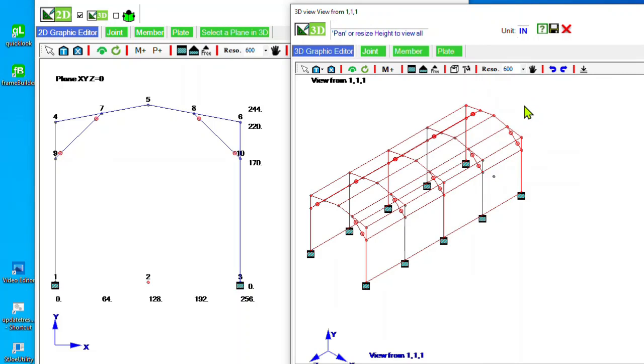Look at the 3D graphic, we have interframe members connecting among supports. We don't need that, let's use the box button to isolate them, thereafter, tag and remove them. There are 2 action buttons unique to the 3D graphic editor. The first one is shaped like a box, the box button. Next to it is the viewpoint button, it is a picture of someone looking through a telescope. Let's use the box button.